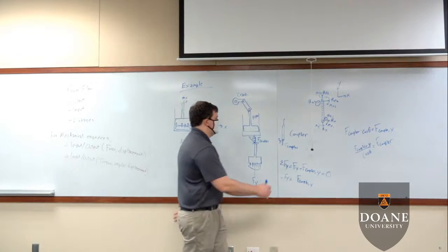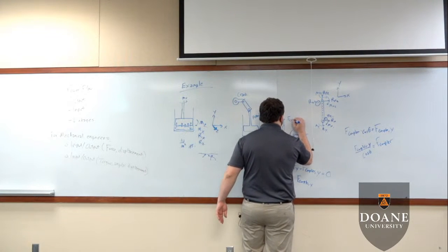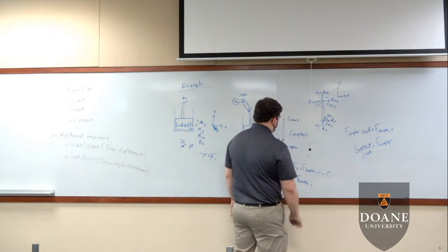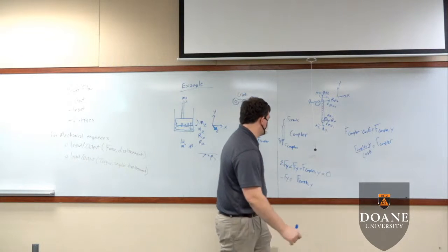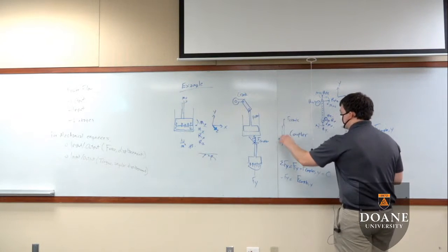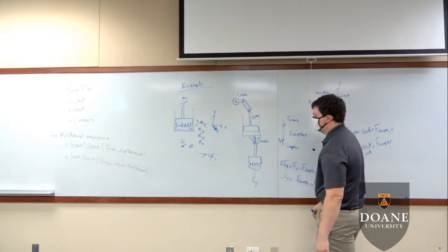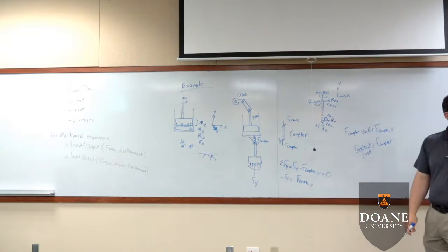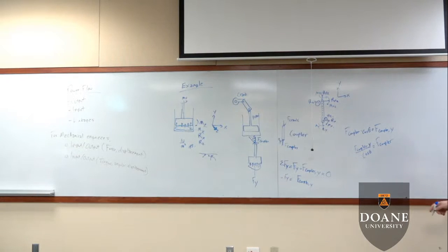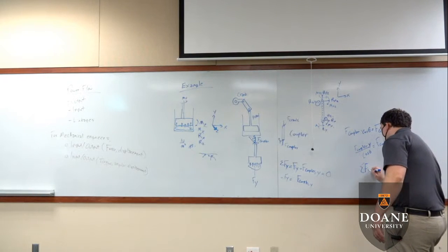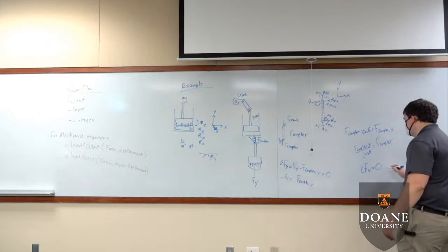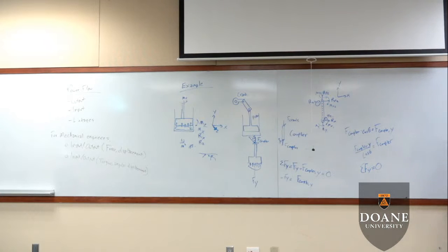Now that I know this, I'm going to go ahead and call this top one F crank. If I just do a quick force analysis there, first of all, this component's going to be in compression. So F crank, probably it better be negative. Otherwise, they're both pointing in the same direction. Sum of the forces in the y direction is equal to 0 because we're going to, again, assume it's not accelerating or that the accelerations are minimal.